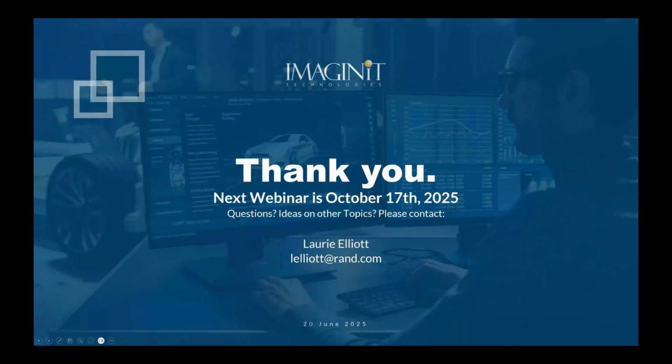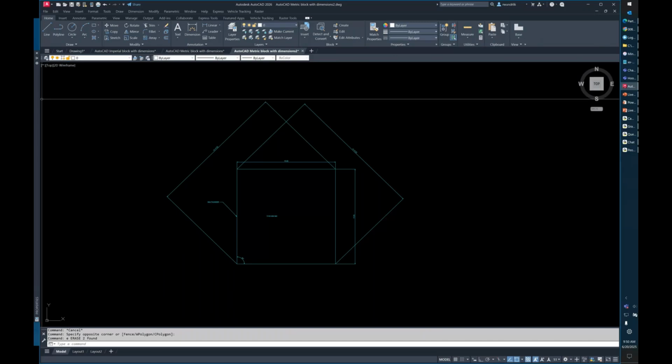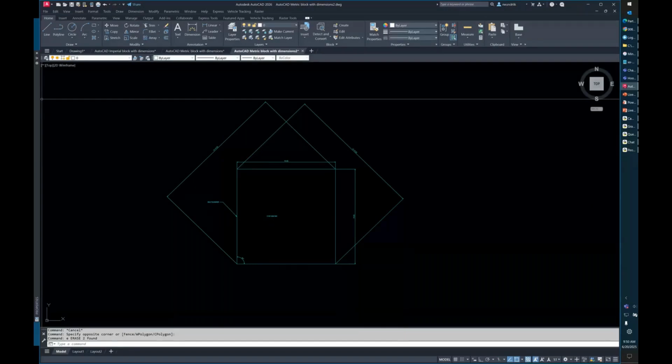Thanks, everyone. Okay, well, working with GPS shape files, once I import them into a drawing, is there any way to keep the original GPS points? Yes, there is a way we can probably keep that GPS data. I'm assuming you're just importing the raw shape file through Map Import. Have you thought about going through the Map task pane to connect to the shape file in order to maintain your GPS data in there?